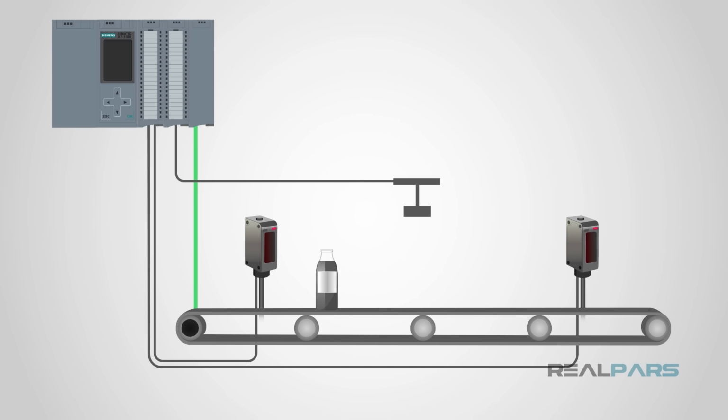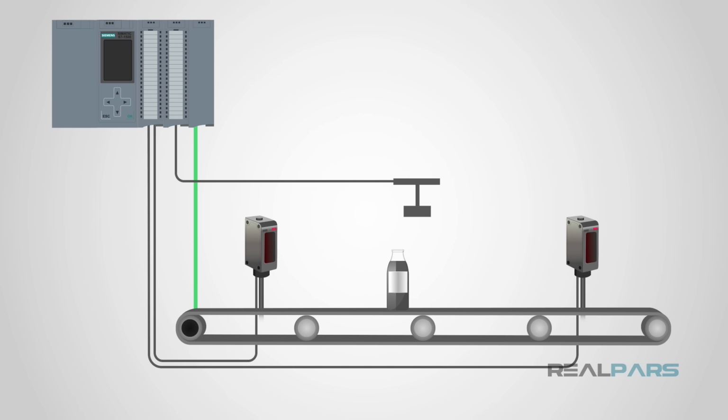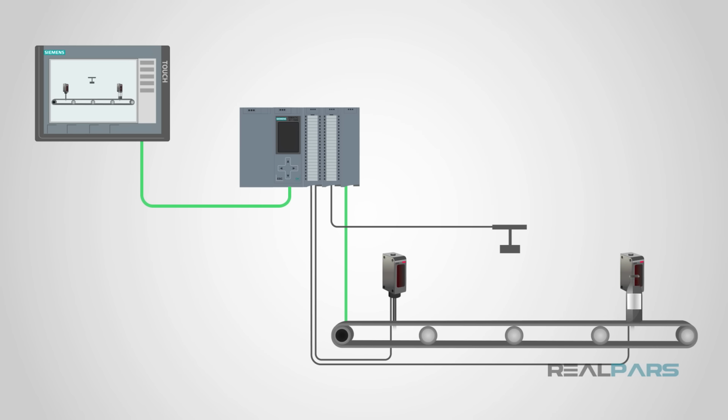PLCs traditionally were used for single batch or high-speed control, have a relatively simple low-cost design, and are the core of the system. Their design is flexible and generic, but completely customizable. Processing time for tasks are typically very fast. Operators usually interact and control the system using some sort of graphical display, such as SCADA.